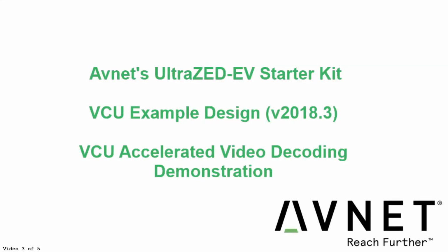Welcome to the third of 5 videos exploring the VCU-based design example for Avnet's UltraZed-EV Starter Kit. This design example enables hardware-accelerated processing of H.264 and H.265 video available in the EV family of Zynq UltraScale Plus MPSoC devices. In the second video in this series, we reviewed the Vivado design scripts for the design example and used these to generate our Vivado block design.